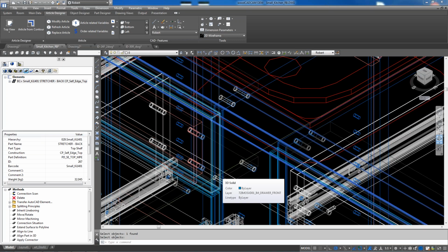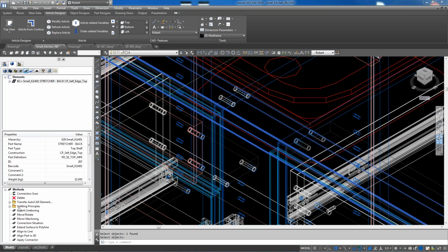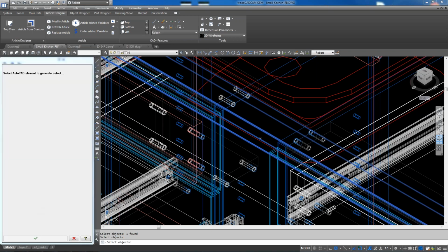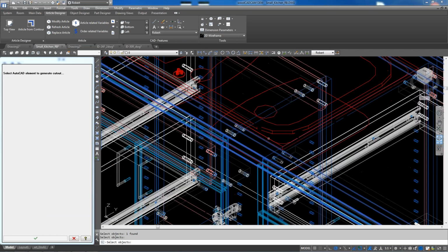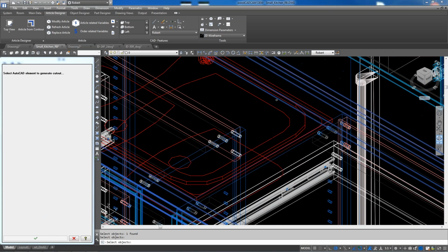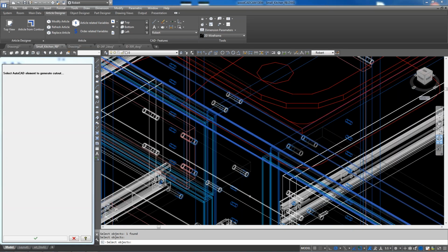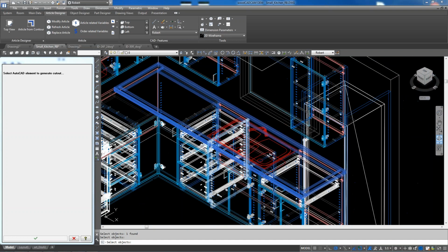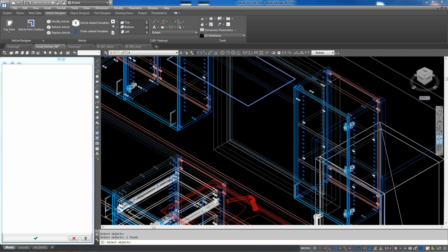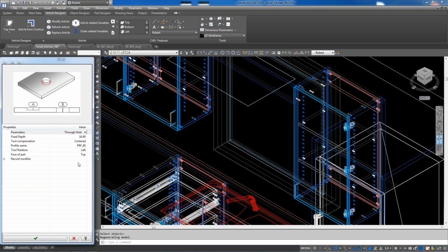All right. So down in your methods, transfer AutoCAD elements. Yep. As inner contour, double click that. Okay. Now select your polyline that you drew. Where is it? It's up on top of the uppers. Oh. Yeah, remember, it doesn't matter where it is in relation to the part as long as it's there. So I got to this point and somehow it didn't work for me. It should be through hole. Through hole. Yeah. All right. So, yep, just go ahead and green check it.